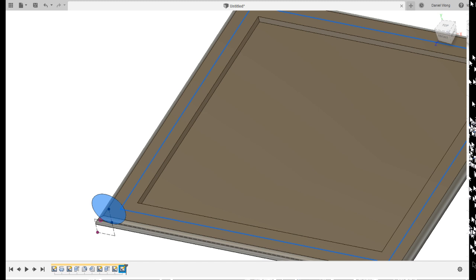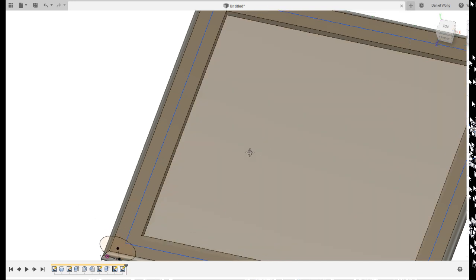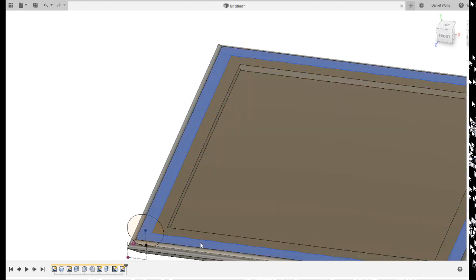Nope, it's not going to let me cut. Great. It's because the sketch is not actually touching. I forgot about that. What we can do to trick that is right-click your sketch. Redefine sketch plane. That's it. You'll notice that my sketch is not actually touching that line there, which means it's not able to make that extruded cut, which is my problem. So sorry about that.